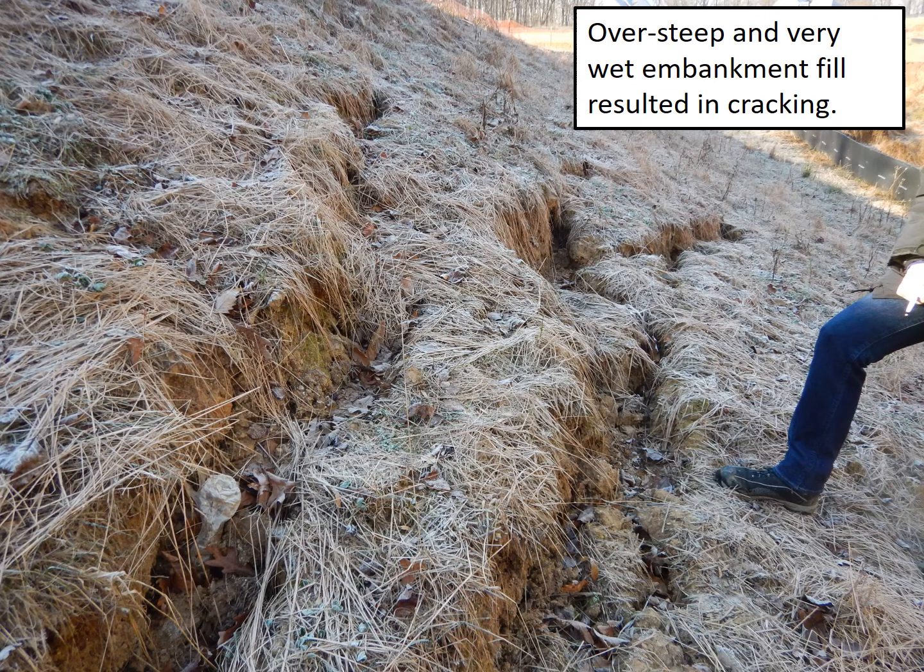Here's an example of a project in Harford County, Maryland, that we got called to. The embankment is oversteep, but also upon reviewing the compaction results, we saw that the material was placed well above optimum. And the combination of those two things resulted in basically the embankment unzipping around the entire structure and slumping down. Those cracks extended pretty deep into the embankment and required some major reconstruction. And I think that all could have been avoided or lessened if there had been better control of the compaction.